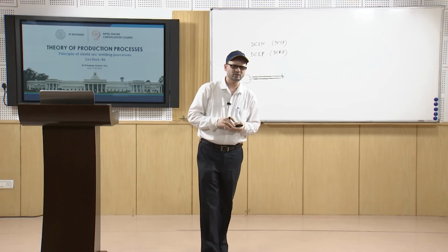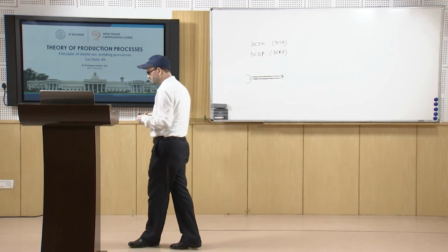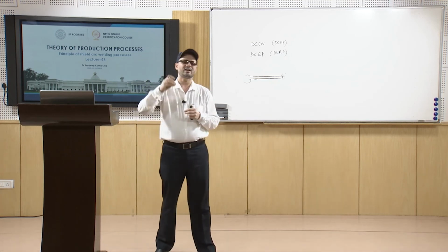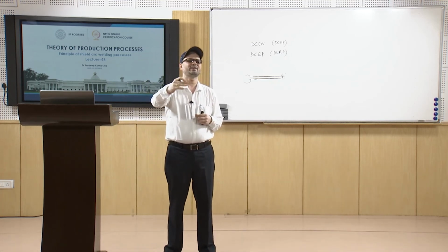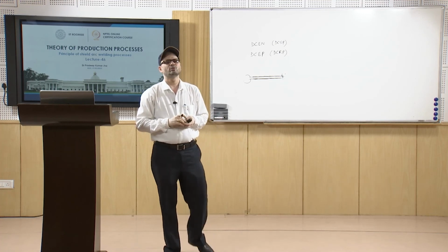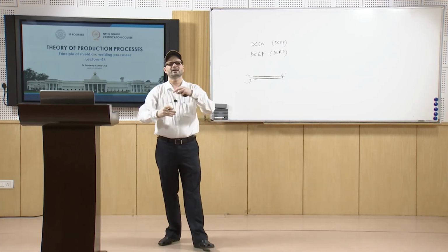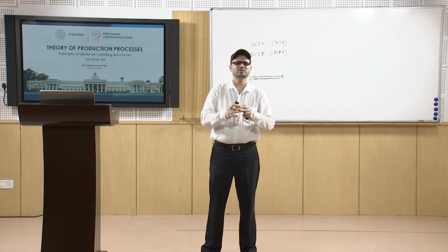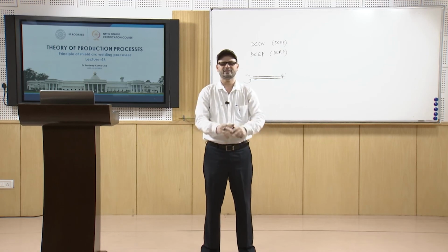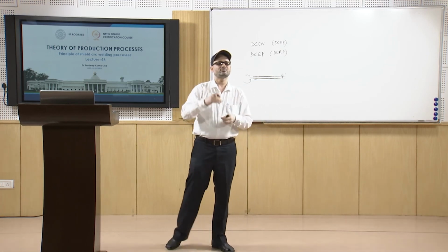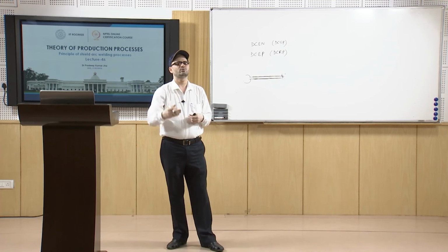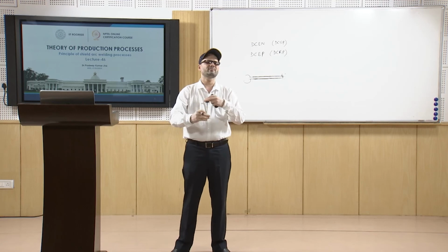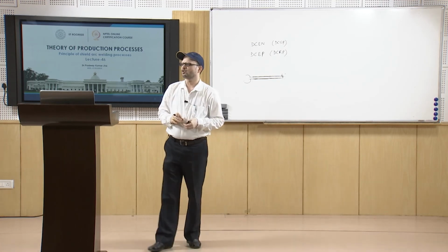As we talk about the operating variables, normally the welding current is of quite a larger value, depending upon the degree of penetration required. You have voltage also. If you take larger voltage, it will cause flame dispersion, so it will heat larger portions. That is the characteristic of a larger voltage. If you have larger current, the penetration will be more. So, depending upon that, the operating variables can be controlled.